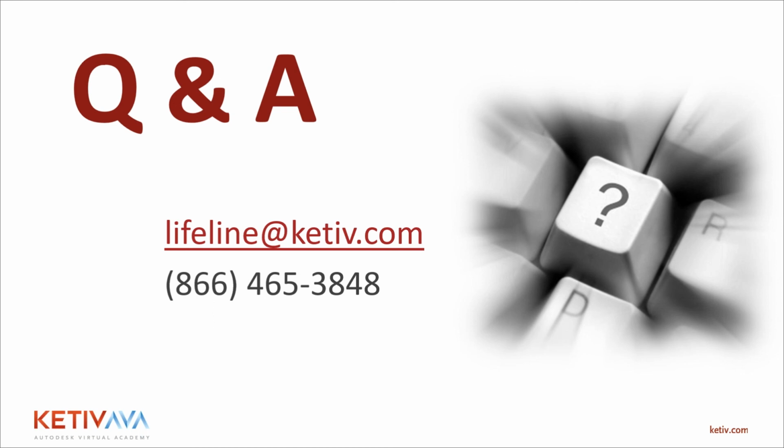So that's that. This question came up literally twice, back to back from different people. And I know we touched on it a little bit, Javier. What's the difference between shrink wrap and shrink wrap substitute? I know that's a question that comes up a lot. So a great question. There's different reasons to create a shrink wrap. You might create a shrink wrap just because you want to send a copy of this assembly to an outside vendor and you want to take out proprietary data. You don't want to create it as a substitute level of detail. So when you create it that way, you can completely disconnect it from the master assembly, send it to somebody, and not worry about them having to connect back to the assembly.